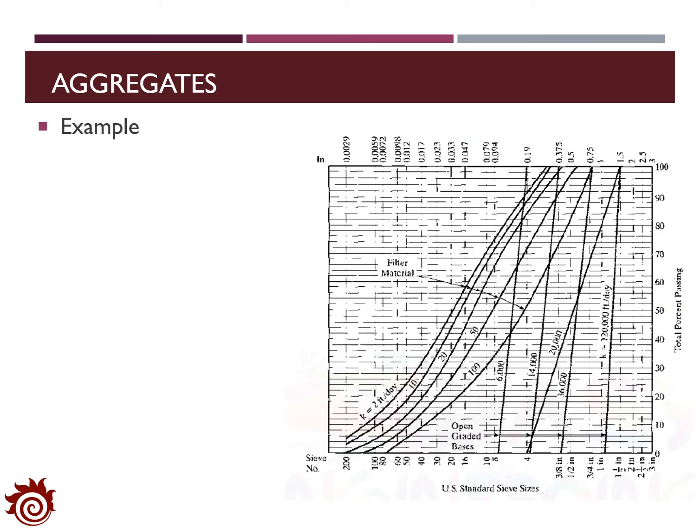From the results in the previous 2 pages, we can summarize the ranges for D15, D50, and D85 for the subbase materials. First, for D15, it should be larger than 0.0065 and smaller than 0.052.